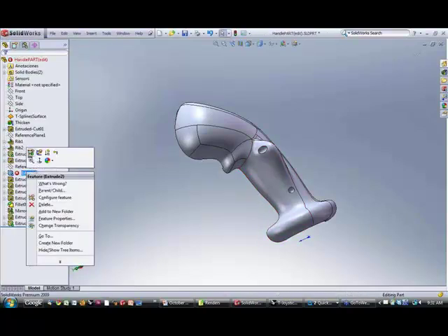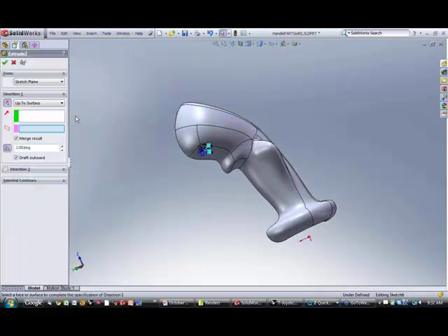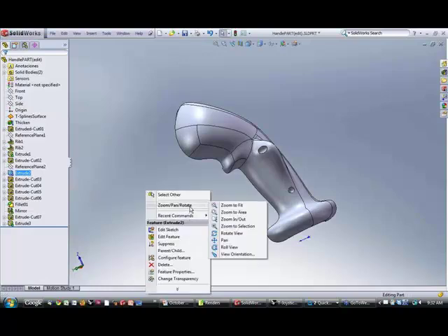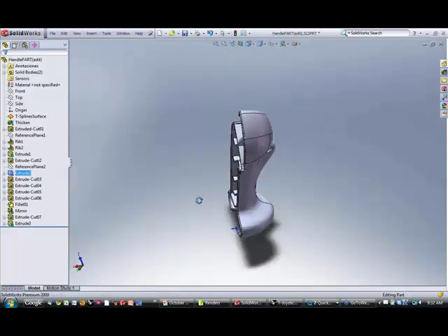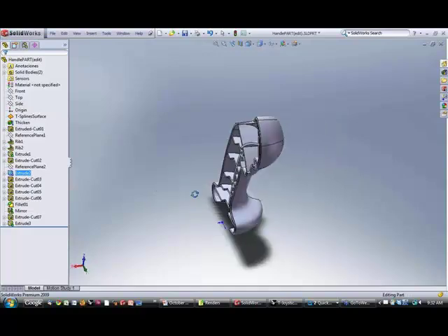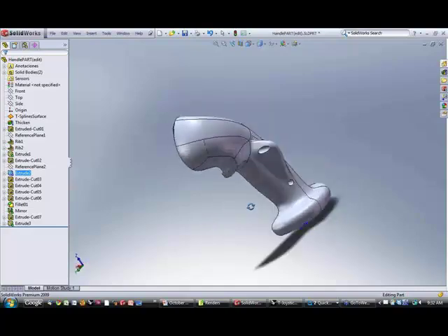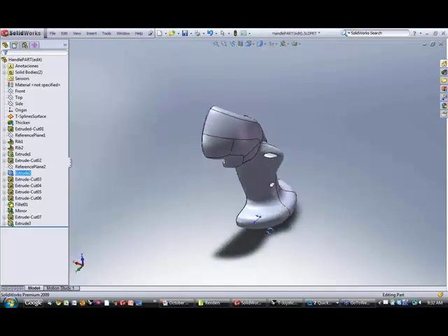And we'll do that again with this one. Edit this feature, and looks like we need to identify that it will come up against this face. And so now we've been able to bring that T-spline model back into SolidWorks and make sure the features are working so that we can check out how this design will work for us as well.